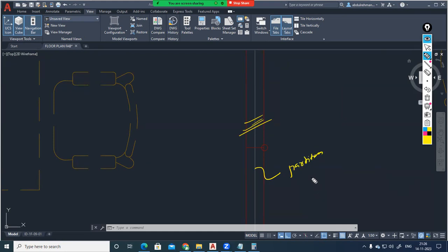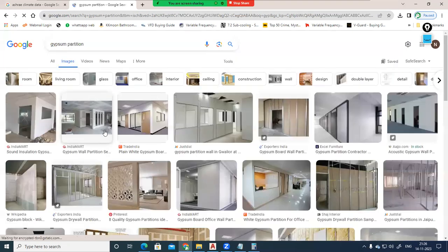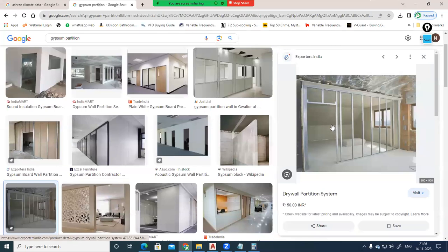Partition, normally, which material are we using? Gypsum only. Gypsum partition wall means in the middle side you'll have a metal frame or stud, as we call it. Then inside and outside, we'll be proposing plaster of Paris, gypsum. So you can avoid plastering cost there. After applying putty and all, you can do the painting on the surface of this plaster.